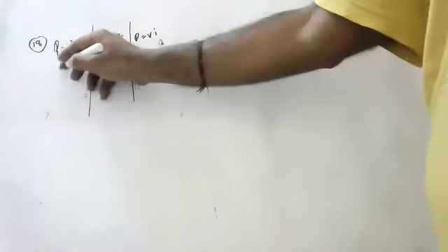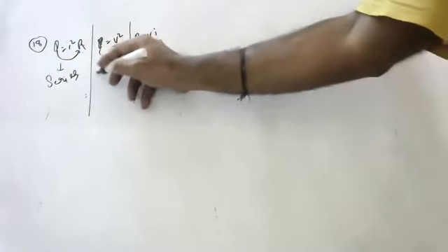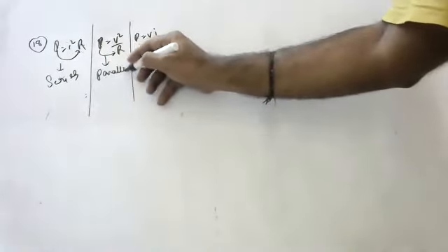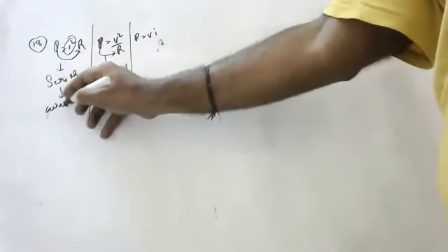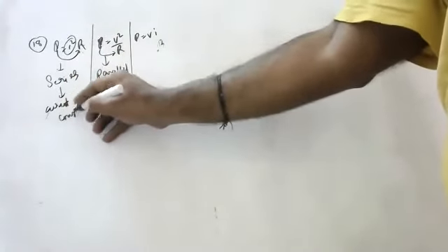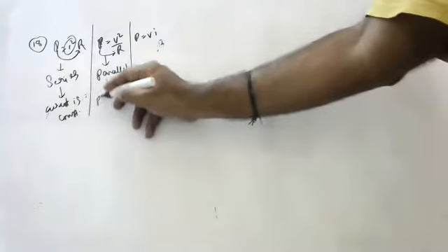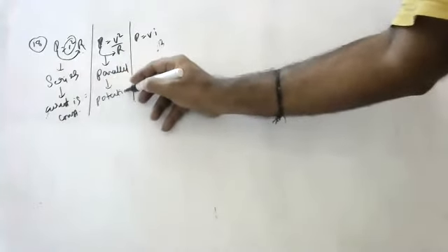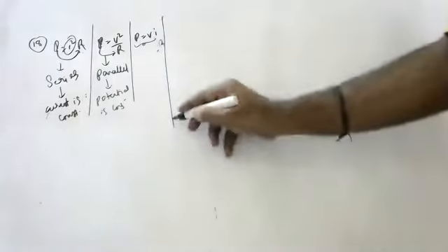Children, this formula we should use in series connection, and this formula we should use in parallel connection. Why, sir? Because current is constant in series. In series, power is directly proportional, whereas power is inversely proportional in parallel because potential is constant in parallel. For mixed connection, we can use either.